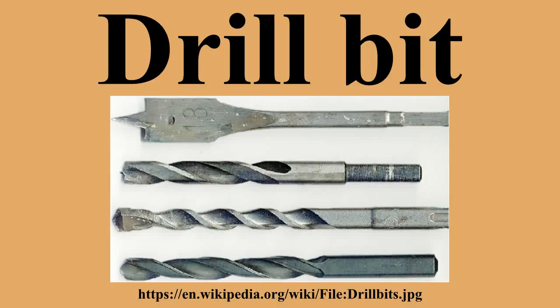Metal spade bit. A spade drill bit for metal is a two-part bit with a tool holder and an insertable tip, called an insert. The inserts come in various sizes that range from 7/16 to 2.5 inches. The tool holder usually has a coolant passage running through it. They are capable of cutting to a depth of about 10 times the bit diameter. This type of drill bit can also be used to make stepped holes.